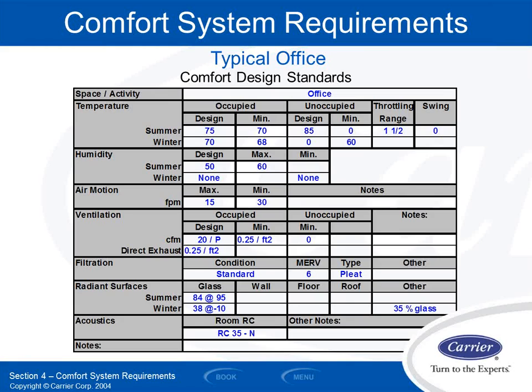Same thing happens on the cooling side with the surface area of the evaporator and condenser. If I can throttle back the refrigeration capacity but keep the same size surface area of my coils, I tend to be more efficient. So what I want to do, if I can design it into my control sequence, is I want to avoid high fire whenever possible. But the flip side, I want to get that less delta T from inside to outside the building during setback to get that savings. So what some of these more sophisticated controls are doing when they're integrated with the actual equipment, they're actually calculating right now what's the best setback for me to have in order for me to not have to go to high fire the next morning.